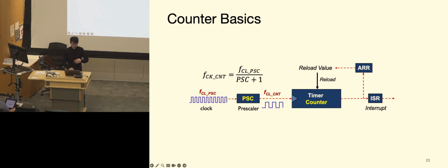At that moment, it also tells the ARR, which is the auto reload register, that whenever the interrupt goes off, that's when you should reload your counter to the previous value and do the counting again, and keep track of when the same event is going to happen next. This happens before it goes to the interrupts, so they are very accurately timed every time, unless something happened during the interrupt that caused all kinds of delays. But it has one layer of protection here.